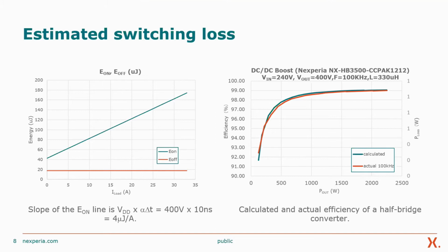It is difficult with a very fast switch to get an accurate measurement of the switching energies from a double pulse test. You invariably add inductance and modify the waveforms. So we also rely on other methods of confirming the switching loss, one of which is using DC-DC converters. It's easy to get a very accurate measure of DC voltage and current in a simple boost or buck converter. And then doing that at various frequencies, you can actually get a good analysis of the switching loss.